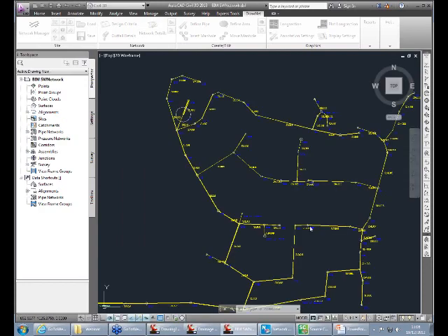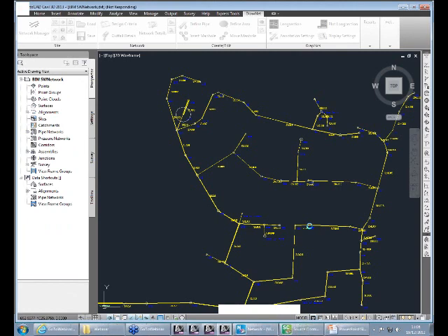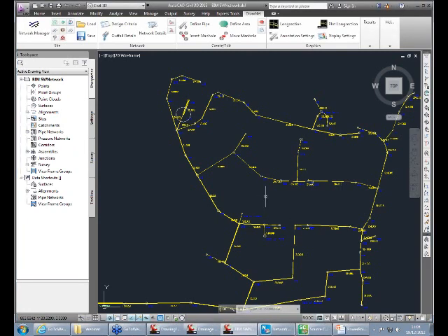That has now been brought in. I like working in this format because you literally are just bringing in that drainage information, albeit I've left the pipe labels on there. I could have just brought in the pipes and the manholes, but of course you can now XREF with your drawings, so that saves quite a bit of memory as well.